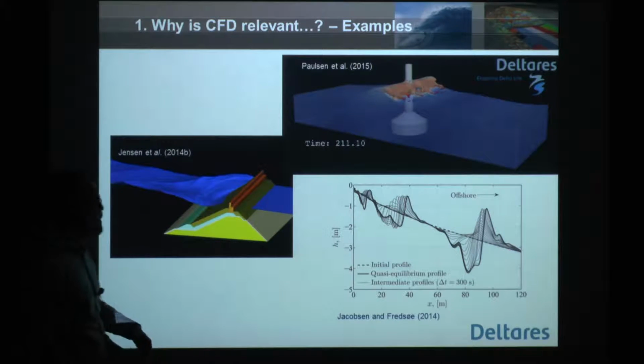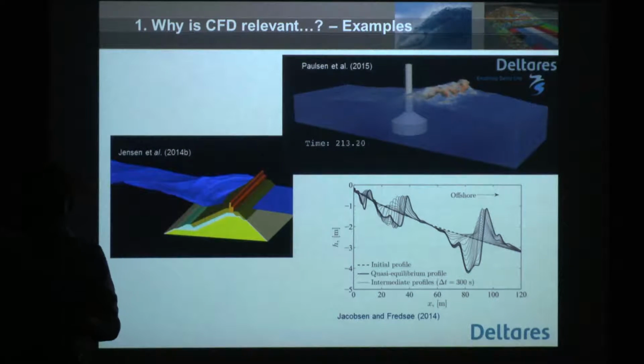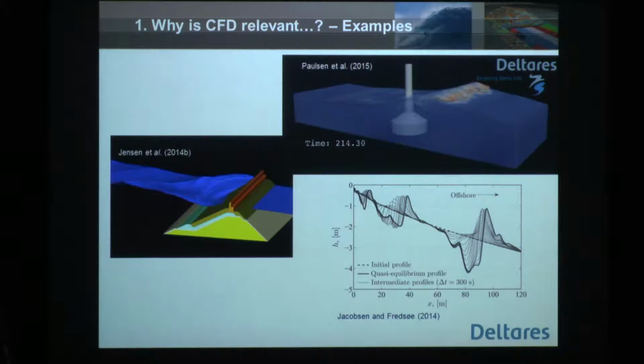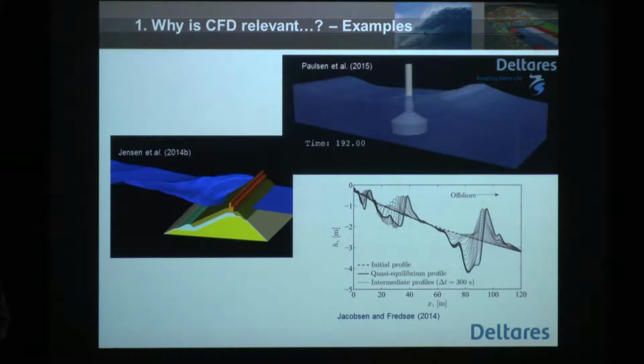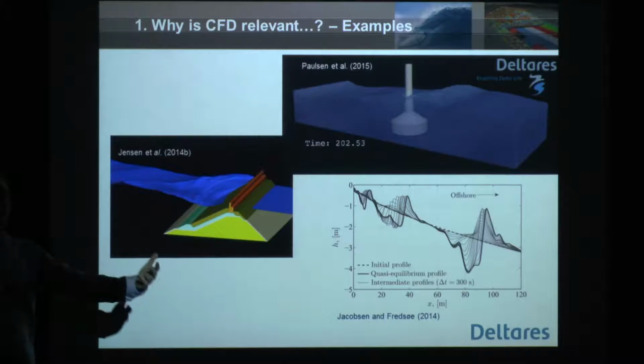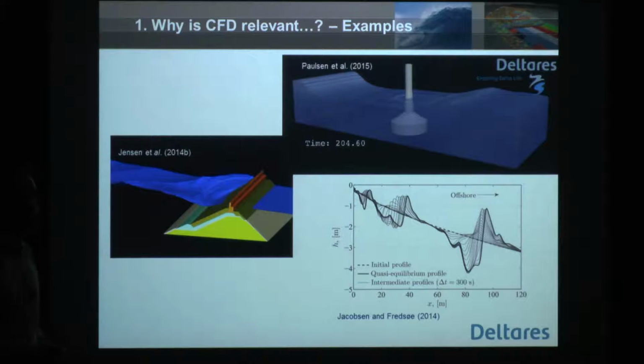But also, the slamming will create run-up on the pile itself. So normally you have to install an inspection platform somewhere above the sea level, but if you put it too low, the run-up will simply tear it apart. And we've seen that in Denmark, where they had to reinstall the inspection platforms because they were simply gone after a couple of winters.